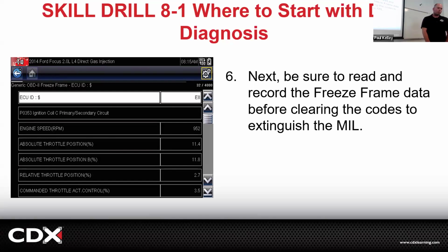If you decide you do want to clear this, you need to record it. You could write it down, or on a lot of scan tools, you can save it as a picture, or in other ones, you can save this as a file. A file you can access later, okay? Because once you clear it, it's gone.